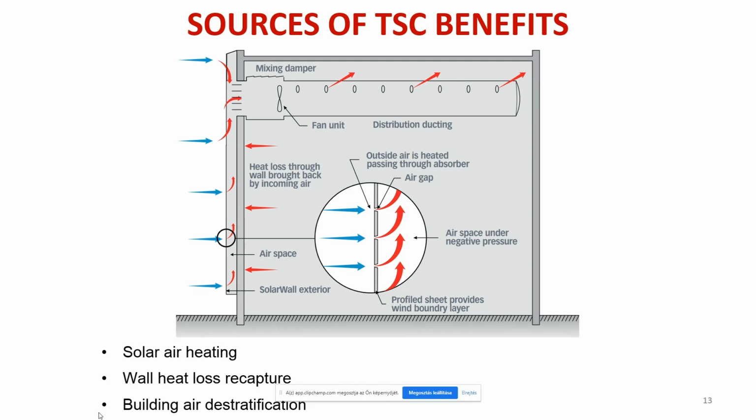Just imagine on the surface of the external wall where you install the transpired solar collector, it is recovering a certain amount of the transmission heat loss, because it creates an airstream in this air gap, and this heat which would go through the wall section normally is being recovered in this airstream, and it's being reintroduced into the building.